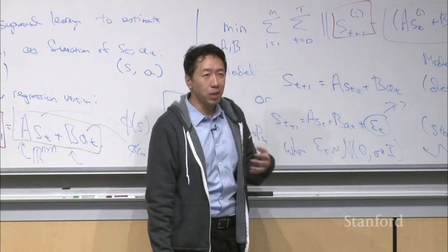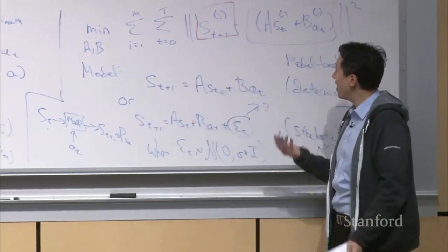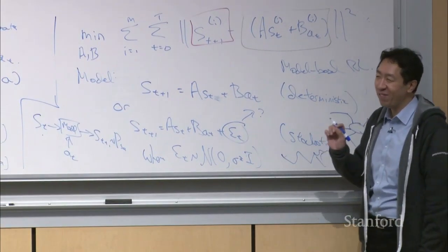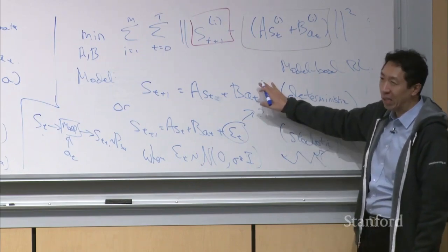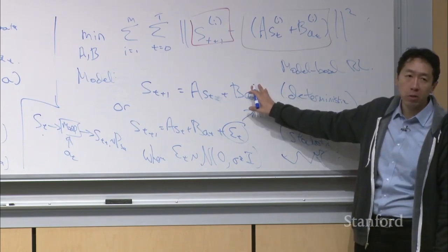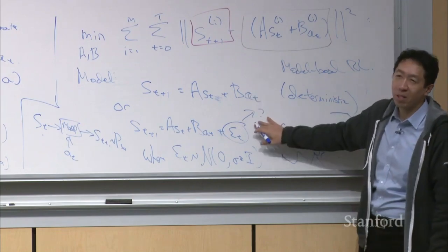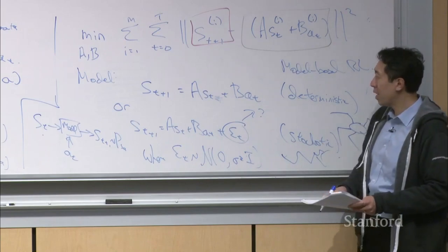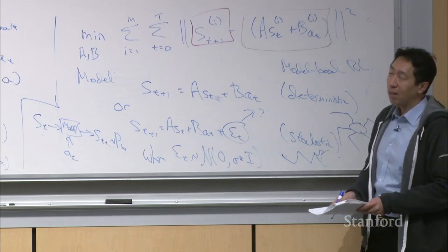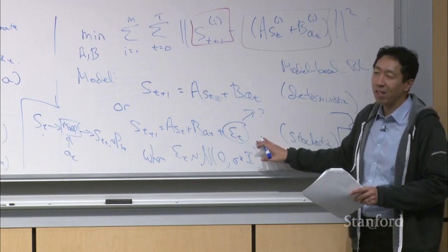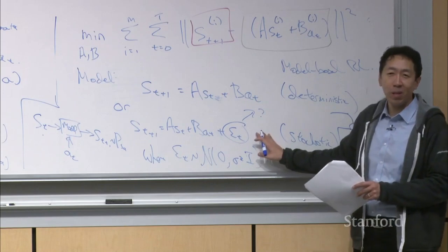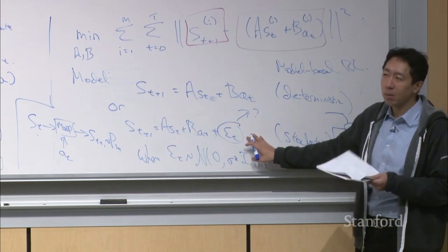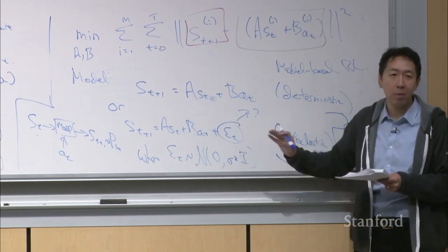So whenever I'm building a robot, with one very narrow exception, LQR, LQG, which we'll talk about next week, I pretty much never use deterministic simulators when working on robotic control problems, assuming I want it to work in the real world as well, right? And again, tips and tricks. The most important thing is to add some noise, and then go ahead and try to pick something realistic, but the exact distribution of noise actually matters less, I want to say, than just remembering to add some noise, right?